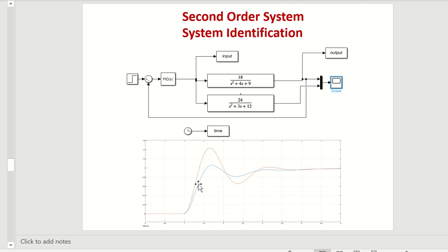Once you've got the frequencies roughly right by getting the natural frequency about right, we can then look at the damping ratio. That's the overshoot and undershoot. There's too much overshoot here. The middle parameter here is the one that controls the damping ratio. If we make that number bigger, you'll put more damping in. Make that number smaller, you'll get less damping in. In this case, you need more damping, so you have to make the number bigger, and that would pull that overshoot and undershoot down.